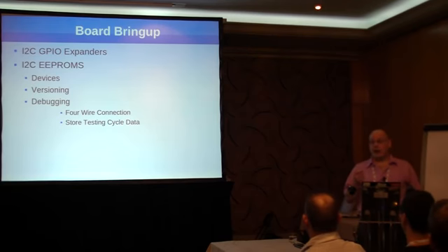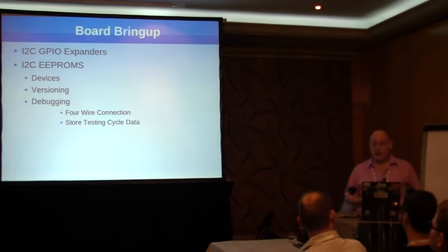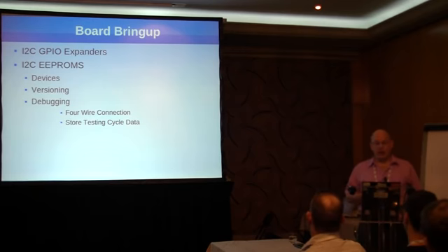Or if a design failure starts cropping up, or it just completely quits working altogether? During the testing, I'm actually writing each cycle value and whether it passed or failed to an EEPROM. So if the board completely blows up, let's say the power or the SoC on that particular board stops working, I can take that serial EEPROM, plug it into another device, and read the last time it cycled and passed, or what was happening on the testing before it failed.